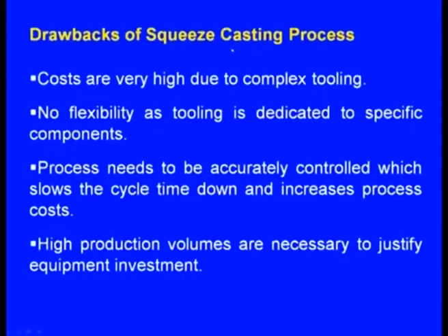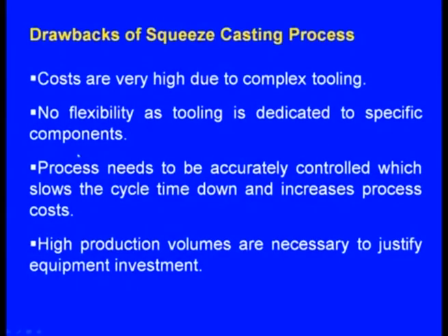Now, these are the drawbacks of squeeze casting process. Costs are very high due to complex tooling. No flexibility, as tooling is dedicated to specific components. That tooling means these dies are meant for making particular components. If we want to make some other components, these dies are to be changed. That is how the cost would go up.